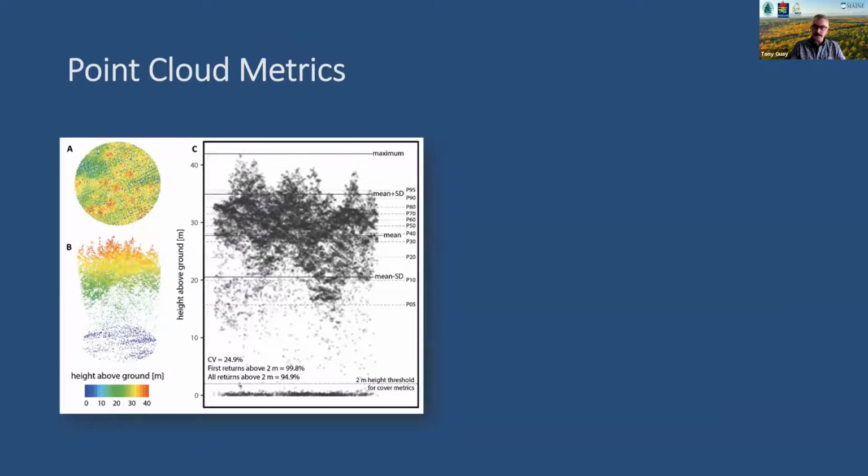And then you've got a series of plot data that's been collected out in your forest, with measurements of things that you want to predict throughout your point cloud, right? And so you'll clip out these plots from your point cloud data. And typically what you're doing is generating what are most commonly referred to as grid metrics or standard metrics, where you're measuring height and density descriptors of the point cloud itself, and you're rasterizing those, and then you're clipping those out for each of your plots.